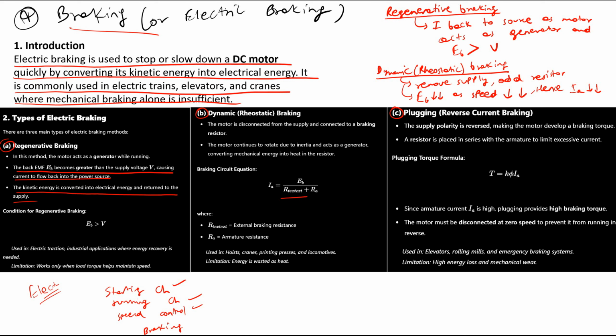Now, the third is plugging. Simply change the polarity of the supply voltage.